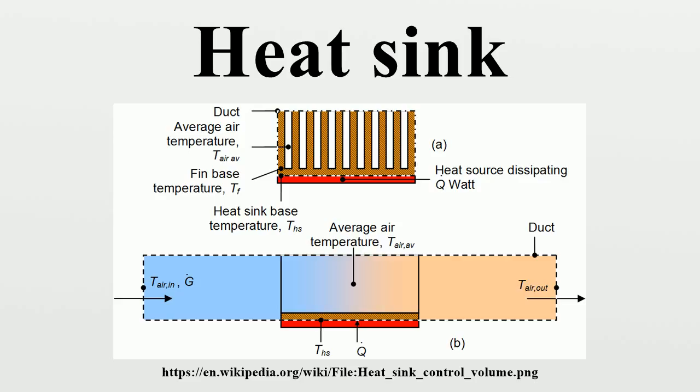Another configuration is the flared fin heatsink. Its fins are not parallel to each other, as shown in Figure 5. Flaring the fins decreases flow resistance and makes more air go through the heatsink fin channel, otherwise more air would bypass the fins. Slanting them keeps the overall dimensions the same, but offers longer fins.